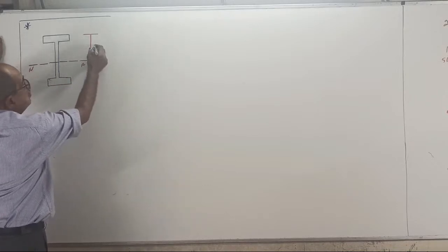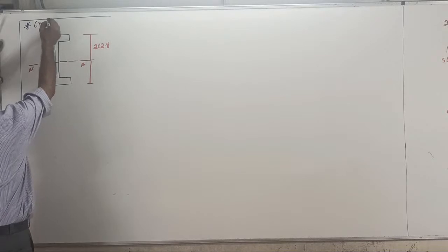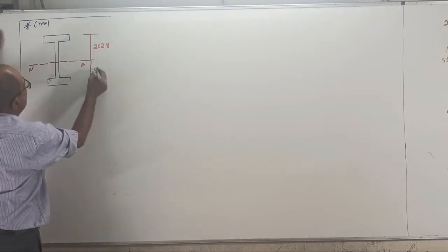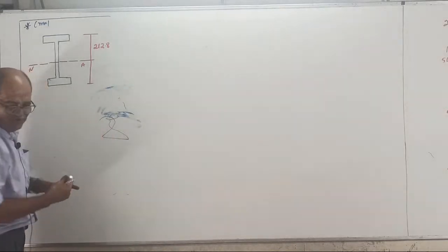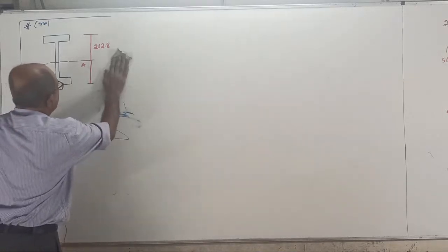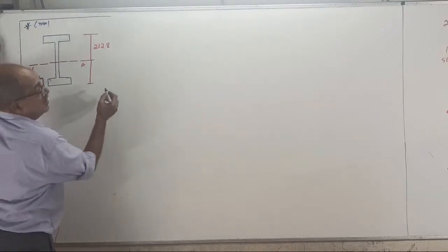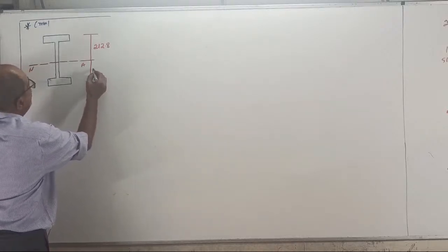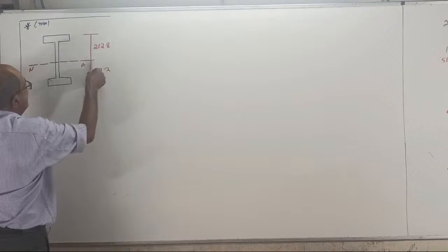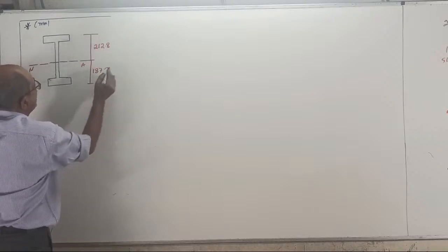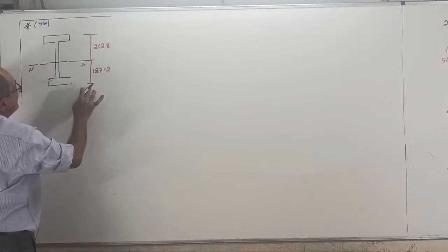This is 212.8 millimeter. Everything is in millimeter. And this is 514. Sorry, what is this one? I am seeing numbers there. It is the moment of inertia. Sometimes what happens is, the moment I put 500, I know it is wrong. This is 187.2. So if I measure here, this is a little bigger, not too much bigger. So here, the top fiber is a little further from the neutral axis than the bottom fiber.